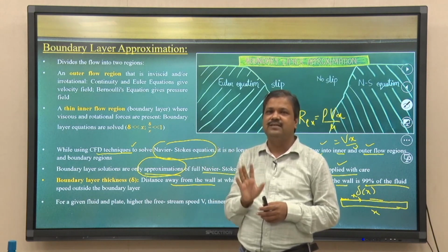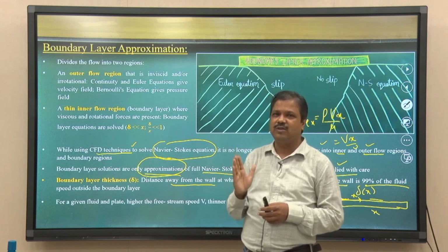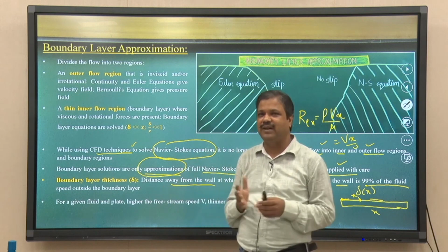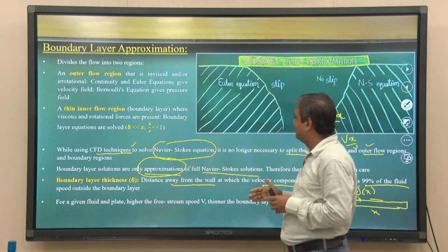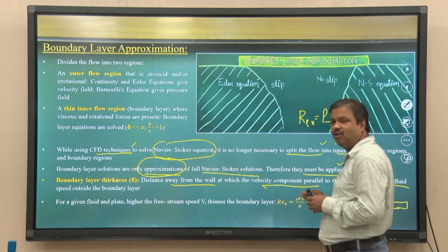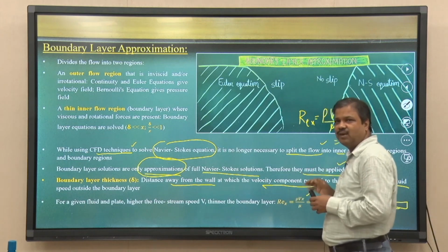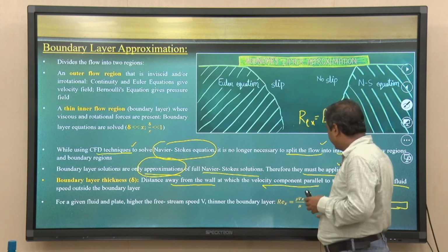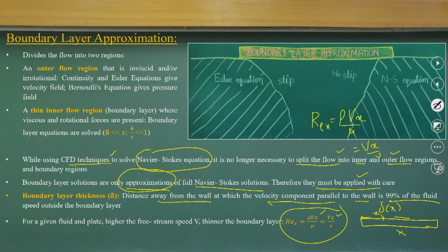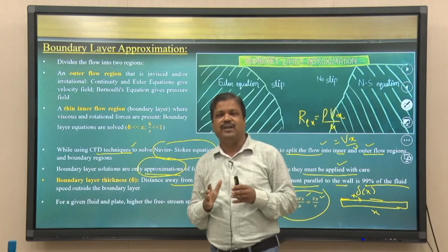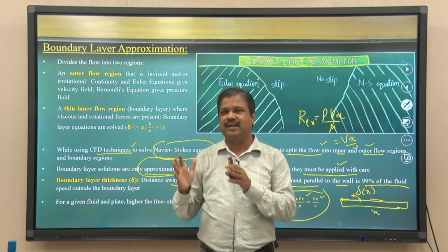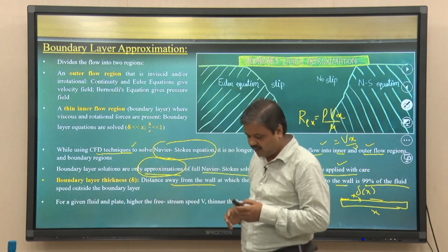So these critical Reynolds numbers are estimated from experimental data, conducted with a plate in a wind tunnel, estimating the velocity observations and the flow field. They tried to find the critical Reynolds numbers to define the three regions in the boundary layer: laminar, transitional and turbulent.